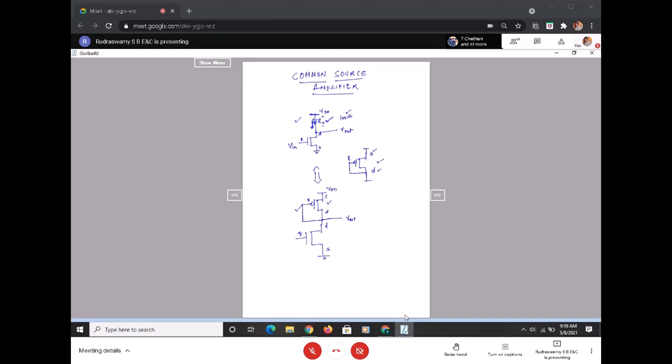All this we have already covered. When this PMOS, that is sitting on top of this NMOS, where the gate is shorted to the drain, will ensure a constant current flowing through it? Anyone? Under what? Saturation. Exactly, it has to be saturation.